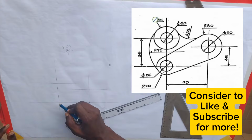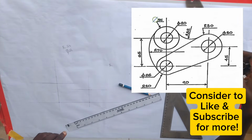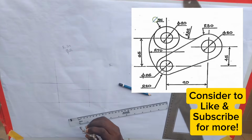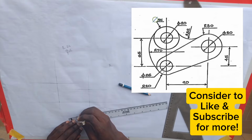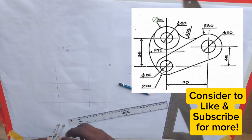Okay, now this small circle is given to be diameter of 26. So the radius will be what? The radius will be 13. So I will measure 13 from my ruler, as this 13 millimeter is same thing as 1.3 centimeter. So I'll place it here.